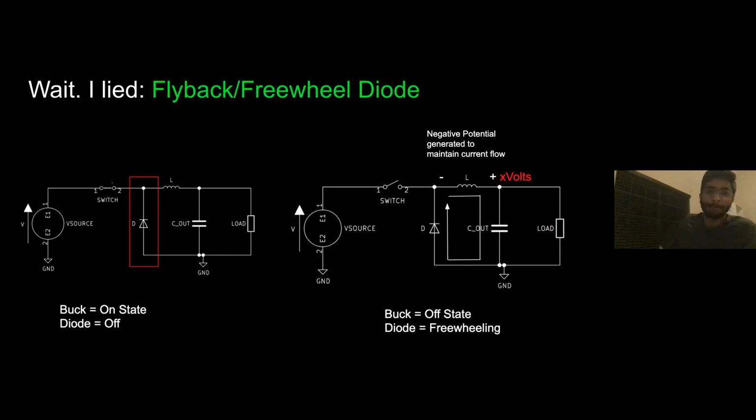It's kind of like, yeah, they're kind of like made of glass, if you think about it in that sense. So how do we combat this? We need some way to dissipate that energy. So we introduce a diode. These diodes are called flyback or freewheeling diodes. What they're doing is providing a path for your newfound current being generated from that field to flow through.